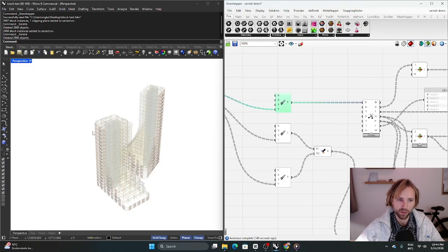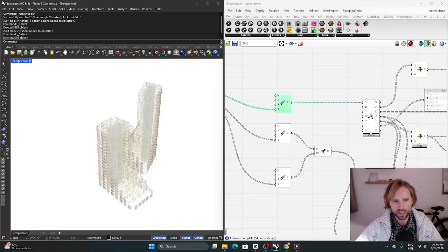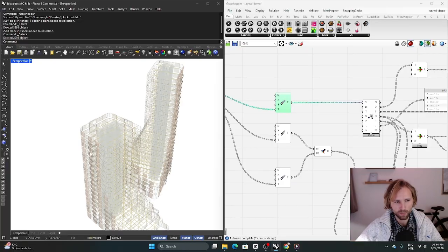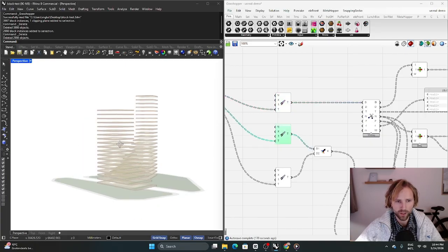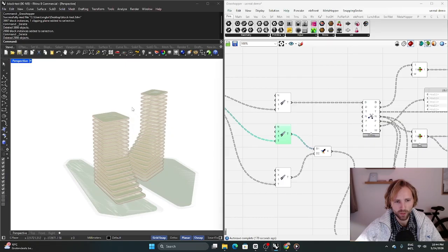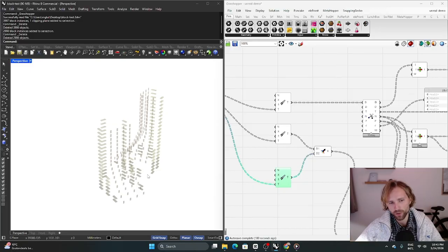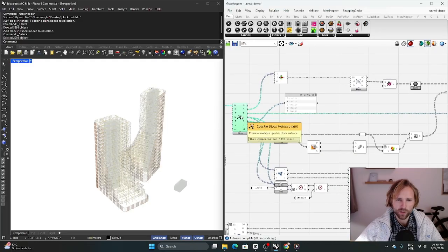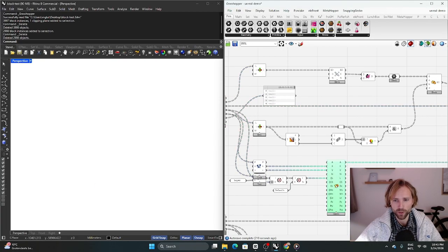Here we have all the block instances. Not everything in this model is blocks, but here we can see that all the columns, beams, balconies, facade elements, windows and so on are repetitive, so that's why we made block instances out of them. But other geometries have maybe not that much complexity or repetition, so they're either a data object or a Speckle geometry. In the next step, we grab all the properties and the transformations from those blocks, and we build Elefront attributes out of them.